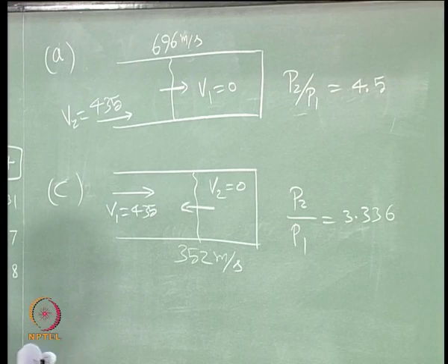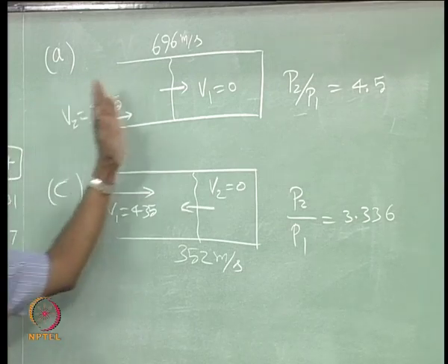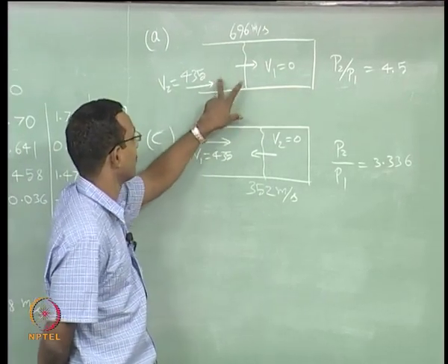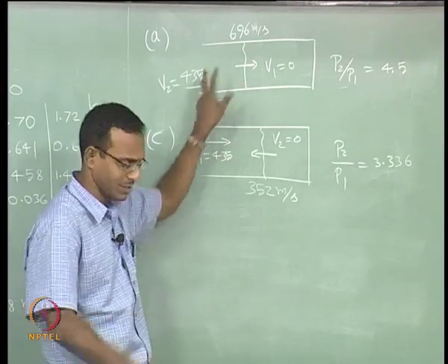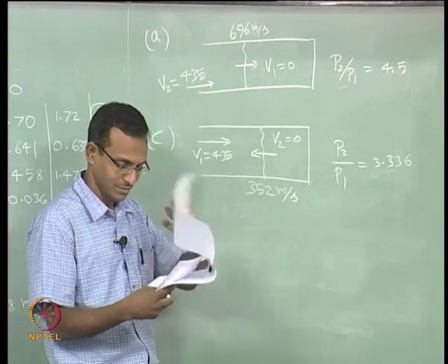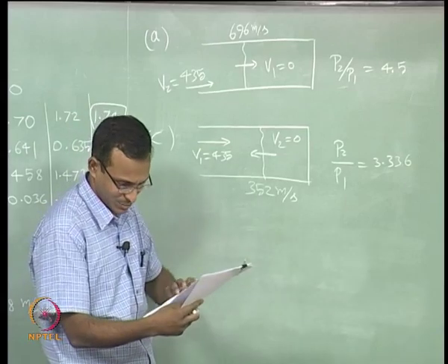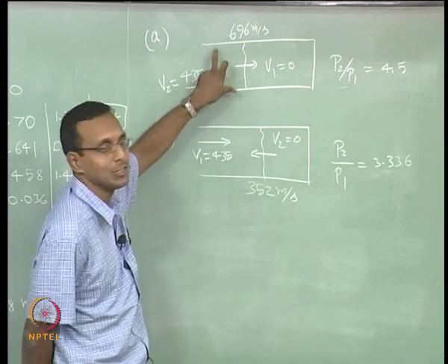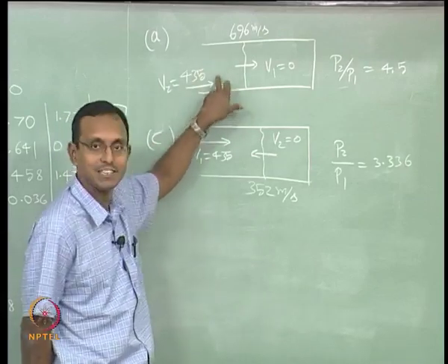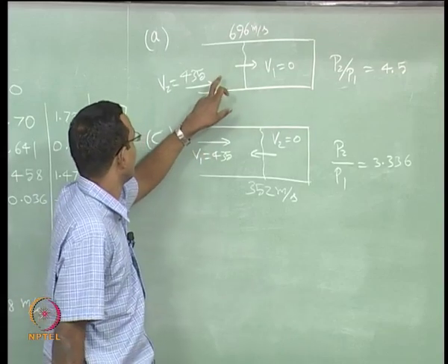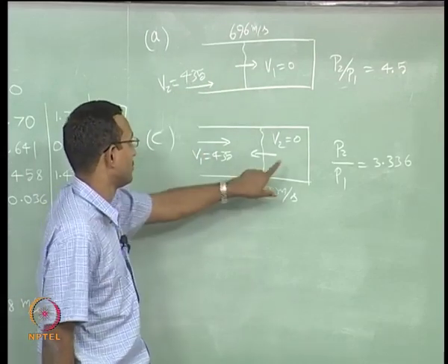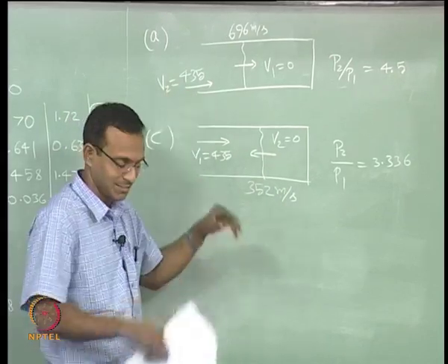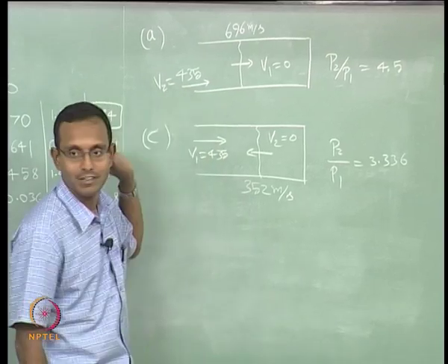So, what we are finding is, when a shock goes first, it has some particular pressure ratio and then it creates a supersonic flow. Actually, it was not supersonic, was it? M2 we did not calculate. I think I calculated, I did not do that part for you. M2 was 0.577. It was not supersonic really, the temperature is also high. Velocity is high and temperature is high, it is still subsonic flow, because the speed of sound for this case, A1 we picked was 450 or something like that, something higher. So it is still a subsonic case somewhere here.